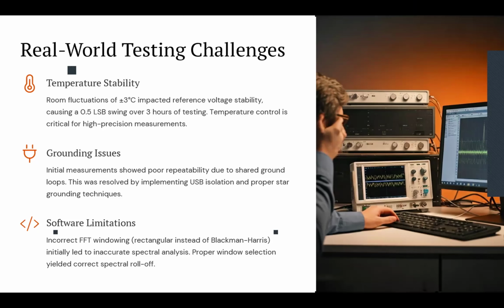So if there is a current injected to the ground, for example, from the signal generator, a portion of that could go to deviate the input of the laptop or the oscilloscope. So we need to avoid that kind of grounding problem and make sure all the equipment are connected to a specific point of the ground and there is no loop between them.